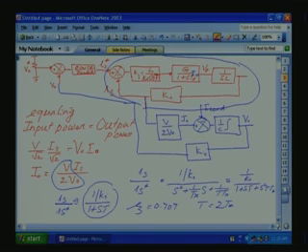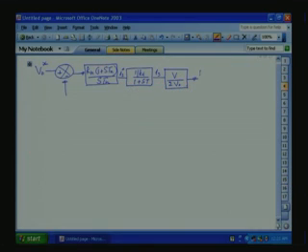This I0 minus I load, if there is a disturbance in load, the difference will go to the capacitor. So let us take a worst case design where full I0 is going to this capacitor, so that we can assume I load is 0. Then we will try to design our controller. So the full I0 will go to the capacitor, so it will be 1 by SC. This is our actual V0. This V0 will be put with a gain kV to bring it to the controller level, and fed back here. This is our closed loop controller.